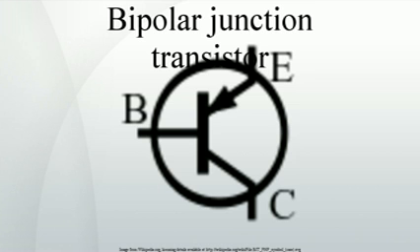Applications. The BJT remains a device that excels in some applications, such as discrete circuit design, due to the very wide selection of BJT types available, and because of its high transconductance and output resistance compared to MOSFETs. The BJT is also the choice for demanding analog circuits, especially for very high-frequency applications, such as radio frequency circuits for wireless systems. Bipolar transistors can be combined with MOSFETs in an integrated circuit by using a BiCMOS process of wafer fabrication to create circuits that take advantage of the application strengths of both types of transistor.